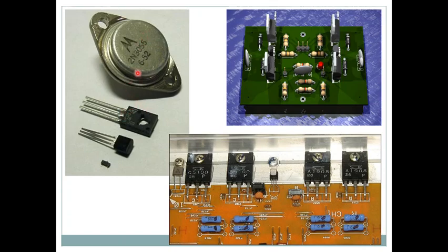And a little bit smaller size like these ones, and here you can see another version. All these types also require heat sinks. They can carry a couple of amperes and they will also generate a larger amount of heat. So if you don't have a heat sink, it may damage the transistor. So they are designed to be attached to a heat sink for heat conduction purposes, to take the heat away. And then we have smaller transistors, through hole type and SMD type.